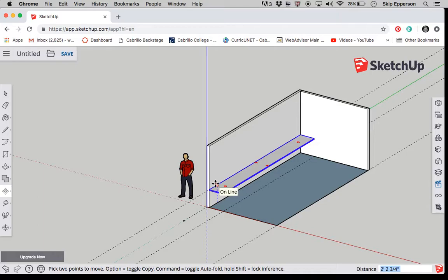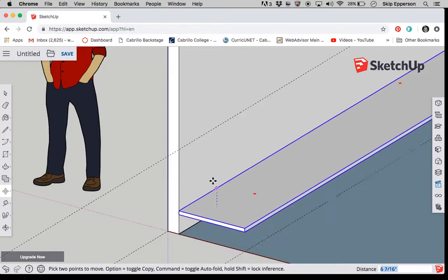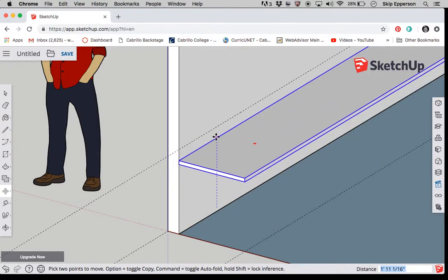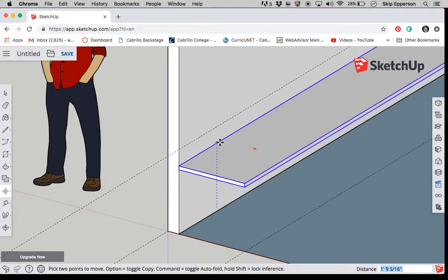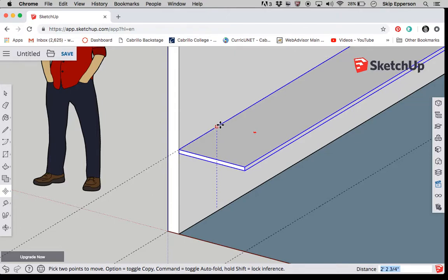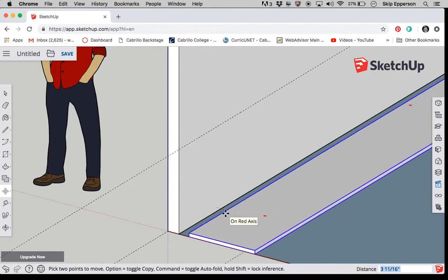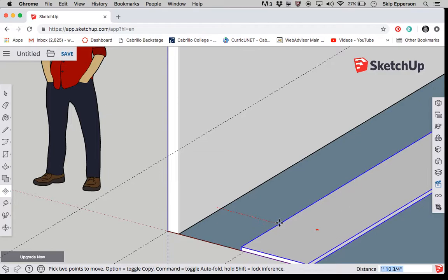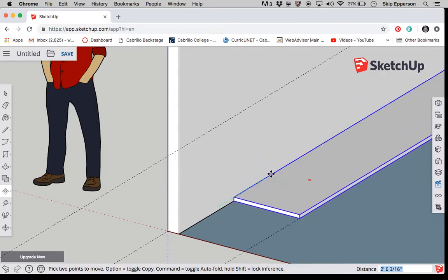This looks pretty good. One thing I want to note when moving around using the move tool is, if you look, moving it straight up, the dotted line is blue, and that follows the z-axis, the up and down axis. If I move it around a little bit, it changes color, has a little red. That moves it in the left-right direction. And the green one moves it up stage, down stage.